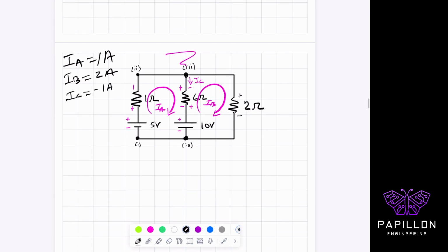So what we're going to do now is put the current back into our circuit. I'm going to delete this just to be a little bit more clear. Because this is the left-hand side, that means that this is 1 ohm. That means that there's 1 amp going through here. Let me highlight that again so you hear it clearly. Right, so that loop has 1 amp. And again, the 6 ohms is very unique because it shares the current between both IA and IB, but that's just an arbitrary value that we made up to help us solve these problems with this technique.